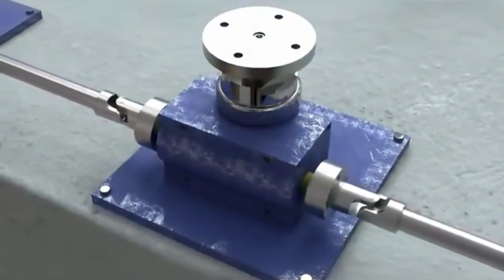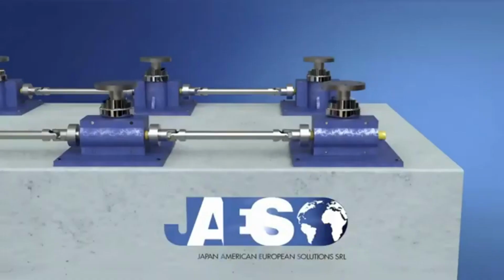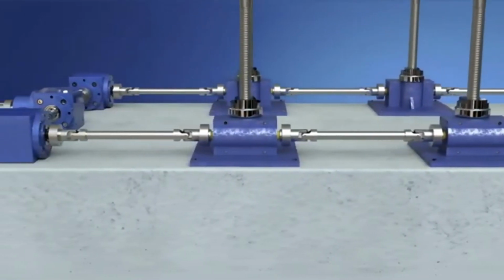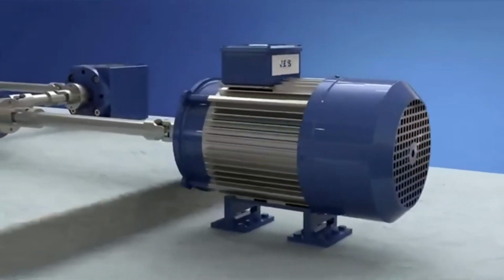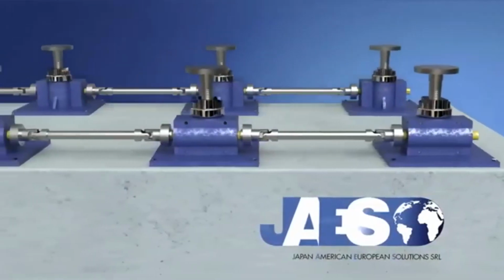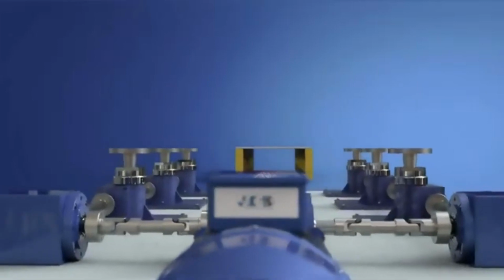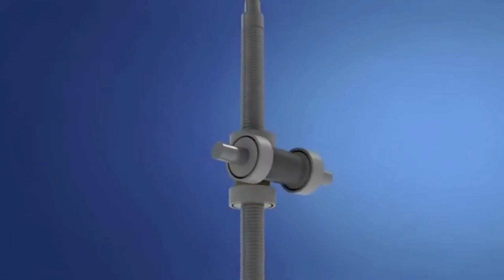A screw jack can be used individually or in a screw jack system configuration. Multiple screw jacks, in fact, can be linked together mechanically or electrically using couplings, drive shafts, gearboxes, and bevel gears, all driven by a single common motor. This allows the creation of real lifting systems designed to work in perfect unison, even in the presence of non-uniform distributed loads.